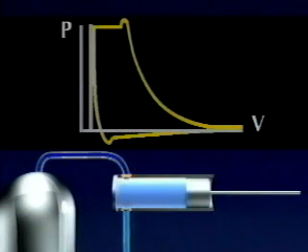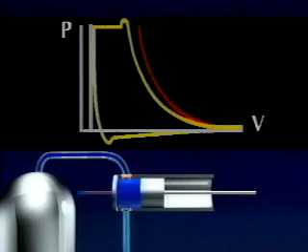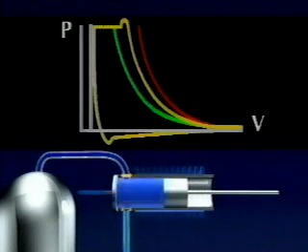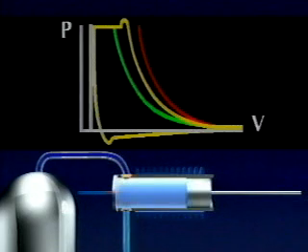If all of the heat of compression is retained, as shown by the red line, we would see the condition we talked about earlier, known as adiabatic compression. But if all the heat is dissipated by cooling, we see a constant temperature in the cylinder, as shown by the green line. This, again, is isothermal compression.